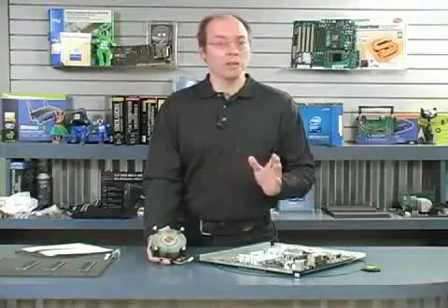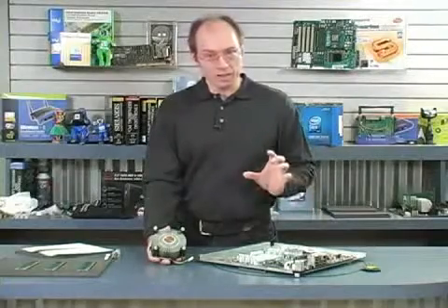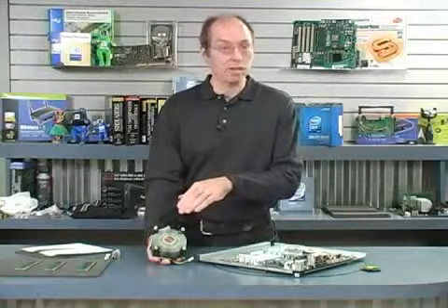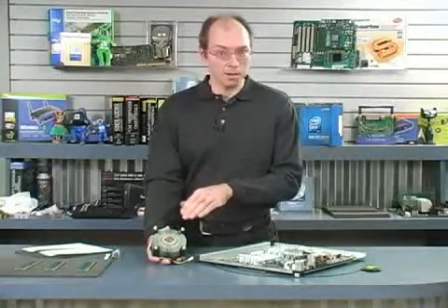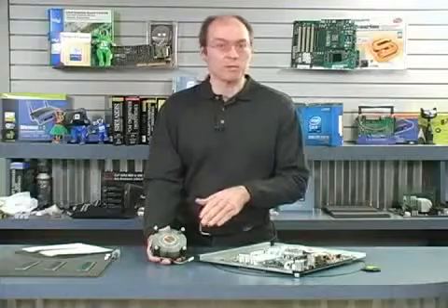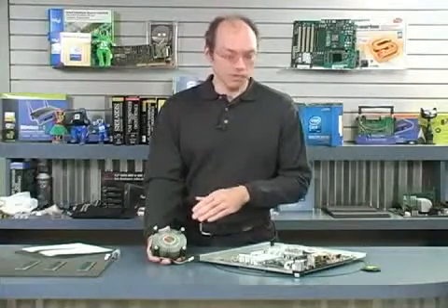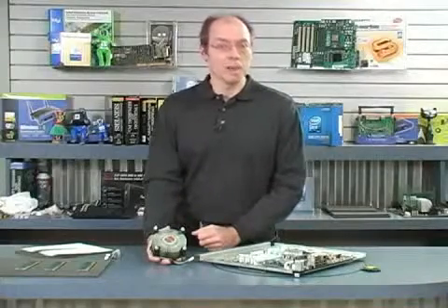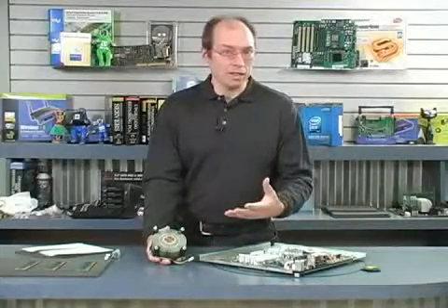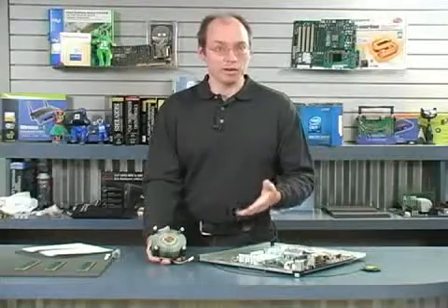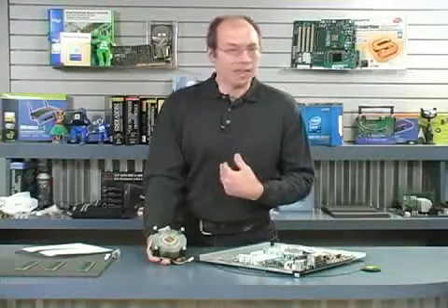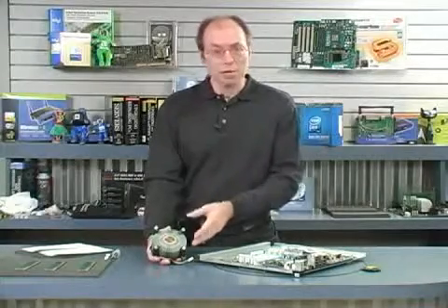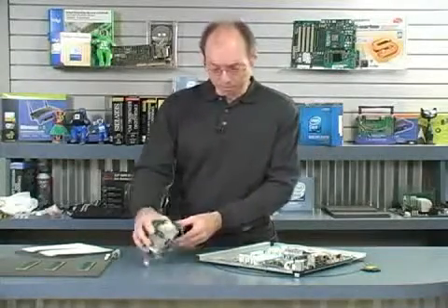Now, with any thermal interface material, once you remove the heatsink, you have to take that thermal interface material and discard it. It has to be cleaned off. Usually you can clean it off with a paper towel. Sometimes you need alcohol to help dissolve all of it. You want to clean it off the top of the processor and the bottom of the heatsink. Every time you reinstall a heatsink, you need to use new thermal interface material. And since, as an individual, I can't really get the phase change stuff, the only way you get that is pre-applied, we have to use what's called a thermal grease.